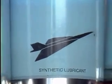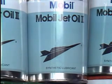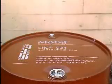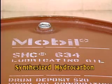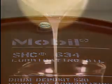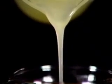Synthetic lubricants are often made from substances found in petroleum and are designed to have the exact properties desired for specific operating conditions. One example of a synthetic lubricant is silicone grease. Silicone grease is highly resistant to oxidation. Synthetic lubricants can generally function in a wide range of temperatures. This synthetic oil is called a synthesized hydrocarbon, or SHC. It's able to continue flowing at very low temperatures and to resist oxidation at very high temperatures.